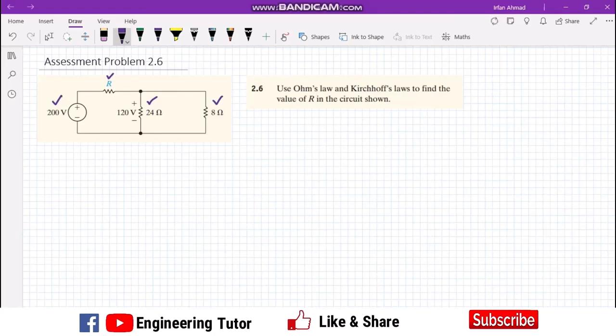As referenced with the previous lecture, we can see here that these two resistors, if this is point 1, this is point 2, and similarly, if this is point 1 and this is point 2, so 1 is connected with 1, 2 is connected with 2. So these two resistors are basically in parallel.